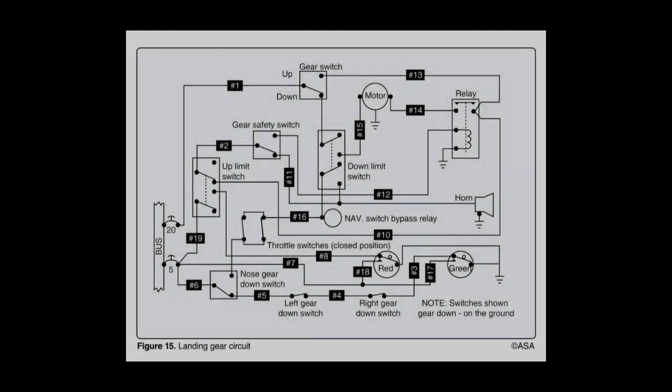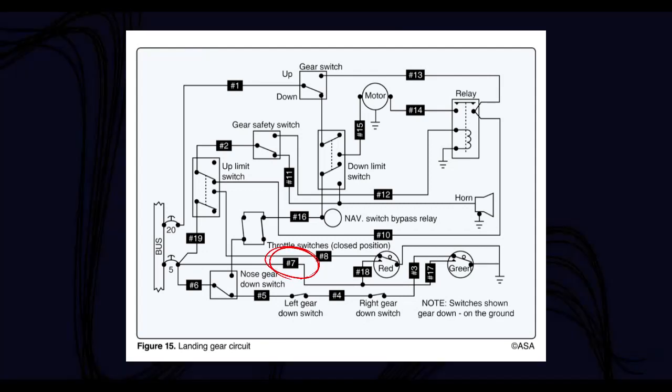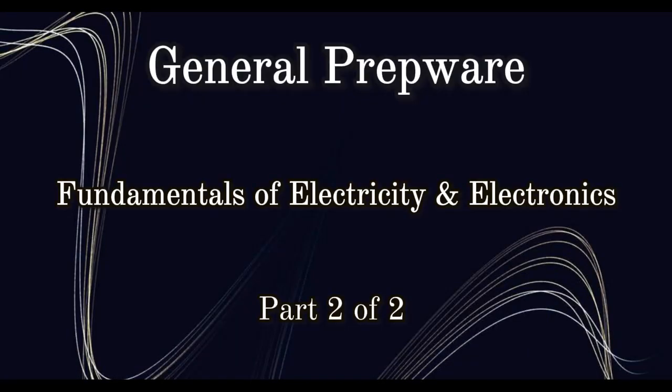Refer to Figure 15. Wire 7 is used to close the push-to-test circuit. What is the likely result, if any, of servicing and charging nickel cadmium and lead acid batteries together in the same service area? Contamination of both types of batteries would occur.